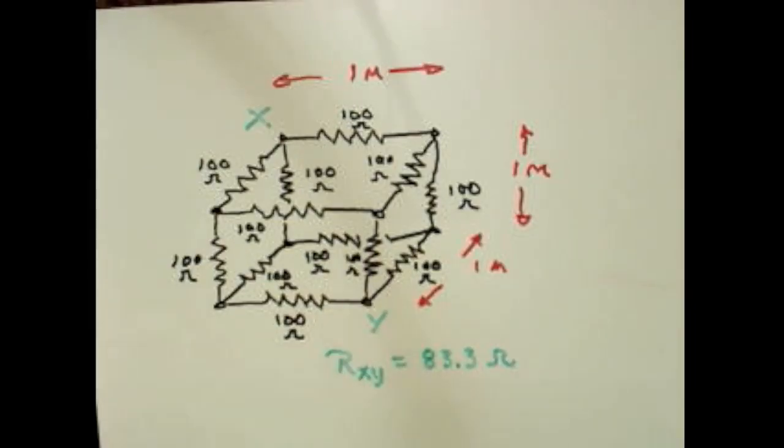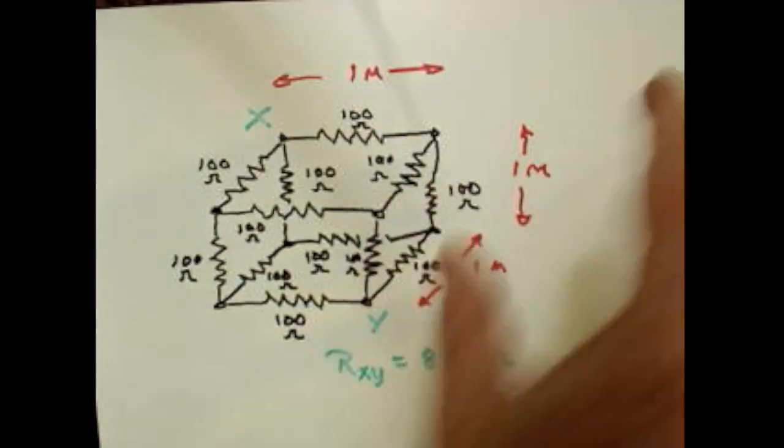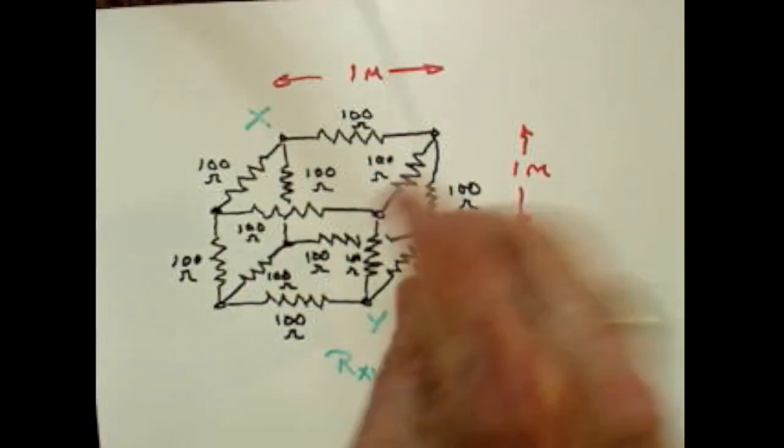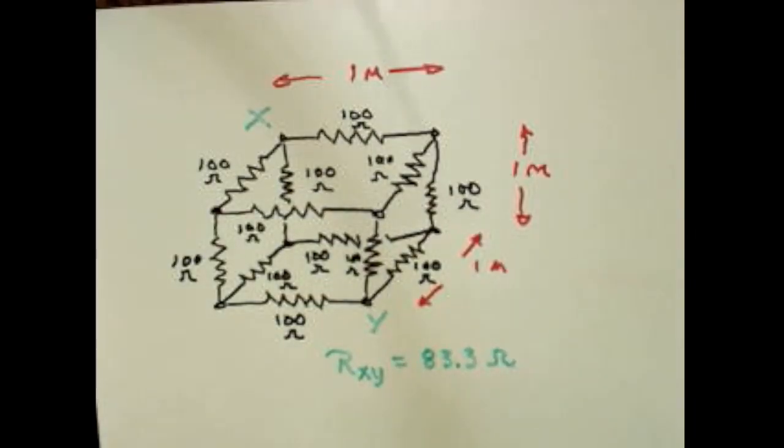Why is the infinite ground somewhere else? And we know that this cube is not in isolation. There's cubes occupying ground in depth, breadth, that makes this a much more complex circuit, but it still yields from the X to the Y 83 ohms. And you've seen how that 83 ohms arrived through various different soil types or ground rod depths.